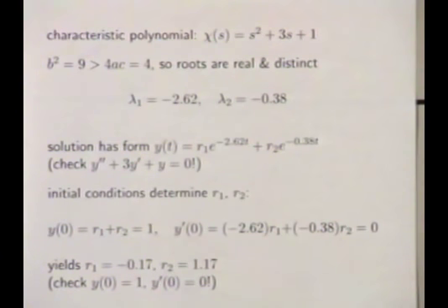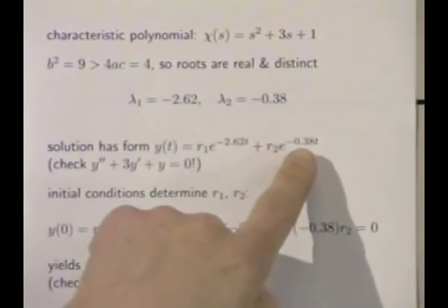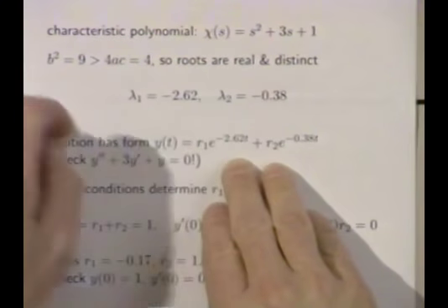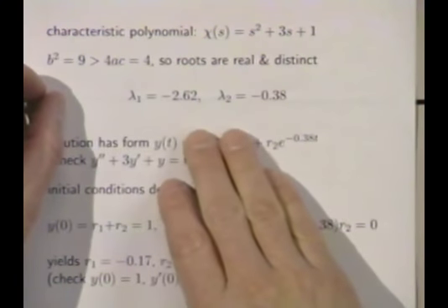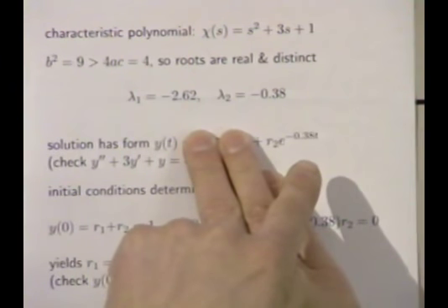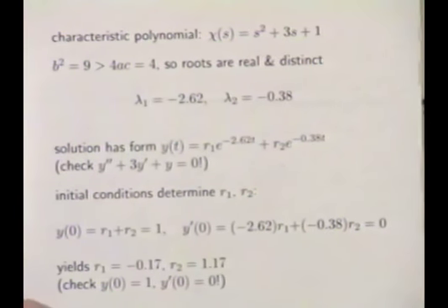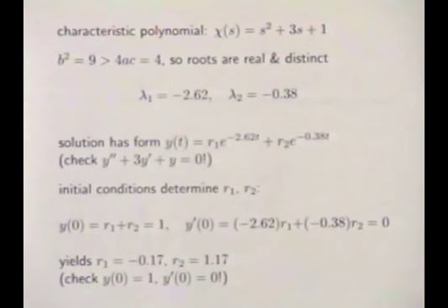Yeah, much smaller, right? I mean, if t is 1 or 2, this thing is much, much smaller than that. So what happens is this term really plays a role only for a little bit of time at the beginning. Very soon, it's just this term. Well, that's kind of neat. It basically says that this second-order circuit with 2 capacitors, something happens at the beginning, but then after that, the thing kind of looks like just an RC circuit. But at the beginning, something fishy, something other happens.